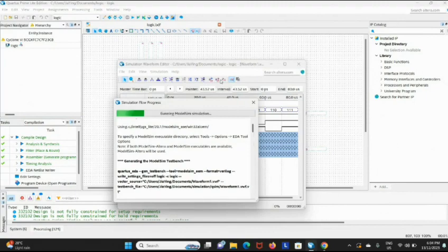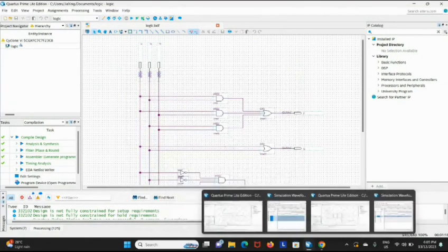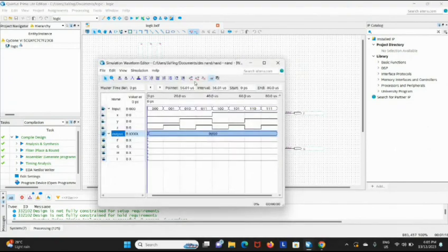The timing simulation will produce a slightly different waveform than the functional simulation, as it contains some delay time. For example, the output of F is delayed by 4.672 nanoseconds, as shown in the waveform. We calculate the delay time by taking the 34.672 nanoseconds labeled by the line and subtracting the 30 nanoseconds of the grid. Hence, we obtain 4.672 nanoseconds of delay time for the output of F in the simple logic circuit. Taking G as an example, the delay time is 4.904 nanoseconds, and the calculation is exactly the same as for F. So now we go to the timing simulation for the NAND connection.